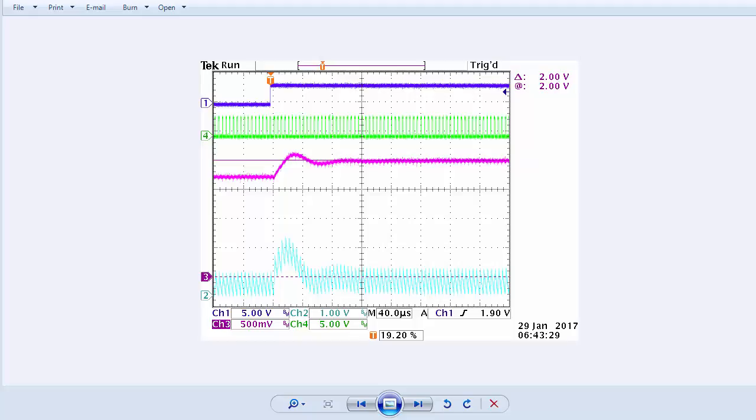Moving on to exercise 3, we're now going to consider a scheme that uses advanced notice of a known load change to completely eliminate the disturbance at the output. The idea is to proactively get out in front of the load change instead of responding to the disturbance after it already happened. What we're going to do is create an open loop sequence in system that adds custom PWM cycles that are exactly synchronized with the known load change to cancel out the output disturbance.